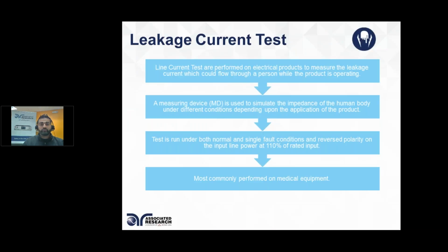And let me quickly describe leakage current testing, as later in the year we do have almost two full webinars designed for leakage current testing. This is similar to what was also known as touch current testing or enclosure testing. But this is a test where the unit actually powers up, and what I mean by powering up is the device is fully powered on and in a normal condition, temperature-wise and power-wise. If you had any kind of software that needs to boot up and then get into a particular state, you want to get your product into that state to perform this leakage current test.